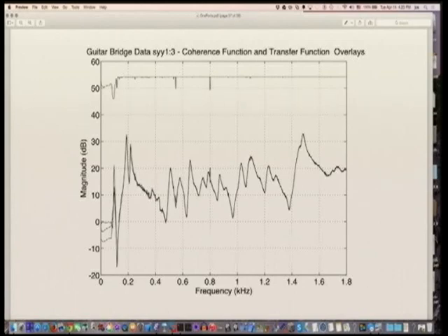So if you have a system with a 0, then you're trying to drive that 0, and it's hard. In this case, it's a mobility. So we have little mobility. That means we have a very high impedance. It means the system did not accept energy at that frequency. It means we got little to no velocity in response. So it means that the noise is significant, and we're not driving up above the measurement noise in our output. So that's a very typical loss.